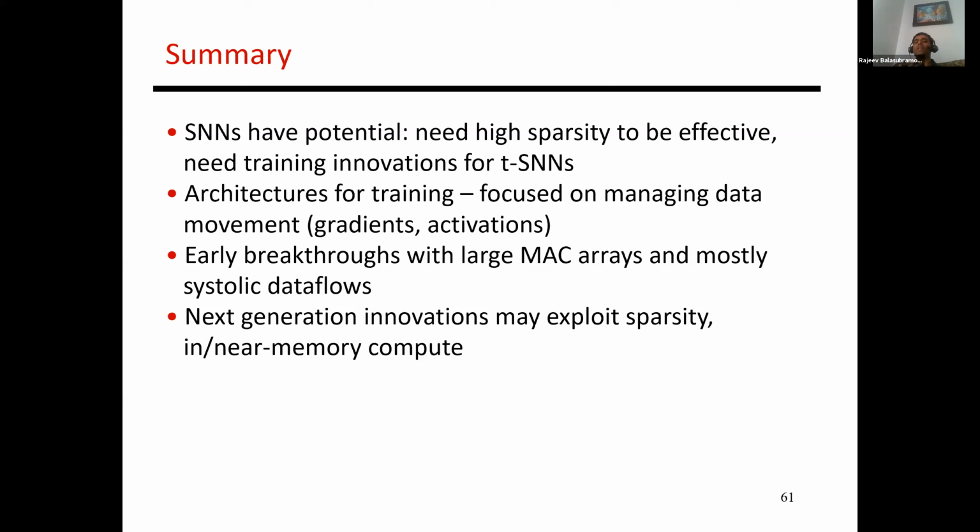In one example, the neural cache does its computations inside the SRAM, which means it does not bring a value into a register and repeatedly reuse it. So it's actually losing locality by doing that. It's minimizing data movement, but maybe you get higher efficiency by having some registers next to the SRAM bank, and that's one way of improving locality and efficiency.